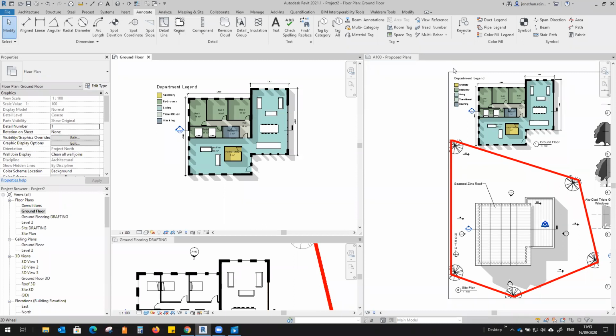In my experience, if you have a surveyor's drawing, it's always good to start from that. In a lot of cases it's going to be a CAD file version of a surveying drawing. So if you have that, you can just trace over those lines. Whether they're straight or not, as long as you're tracing over what's been surveyed, it's the most accurate level of modeling.